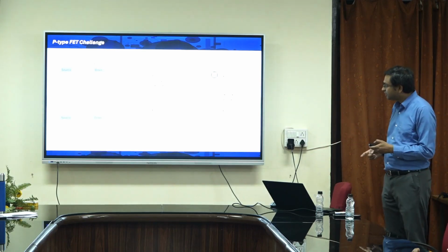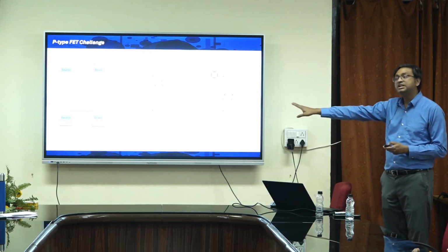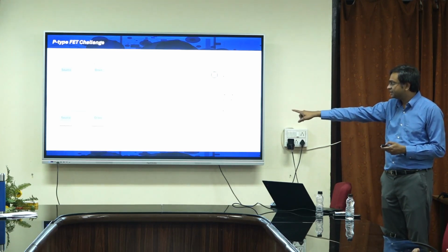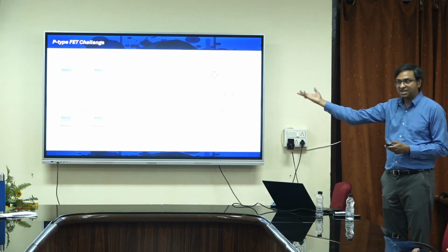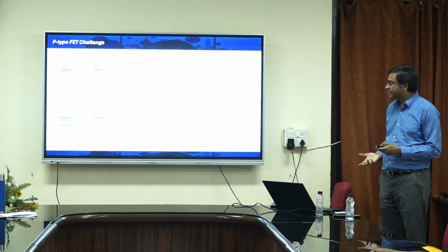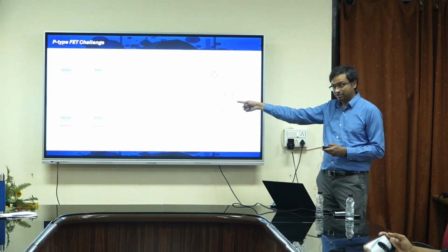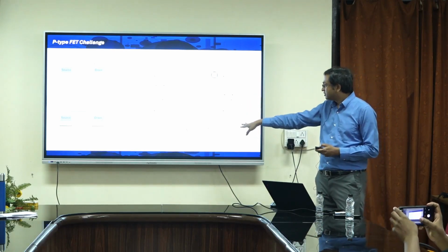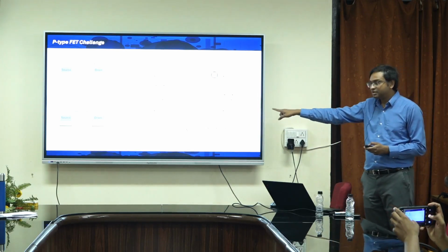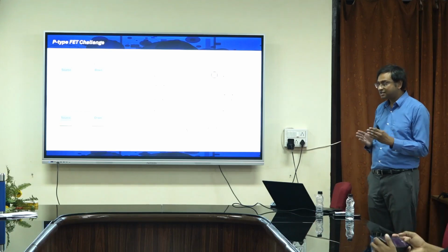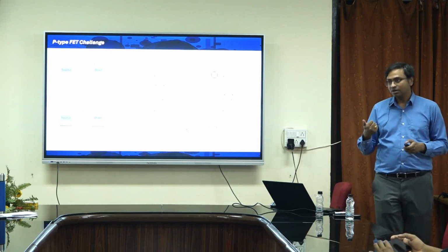So this problem is mitigated in silicon, as I told you, through degenerate doping, because in degenerate doping you use a P++ contact, and you make the channel intrinsic or N-type or whatever it is, and that's how you get to a very thin Schottky barrier width. And this is again going back to the same formula that we discussed in the previous lecture: by degenerately doping, ND has to be very large, then I have a good contact. So the question now is, how do we do it for P-type 2D FET?